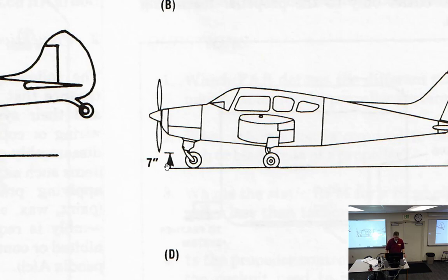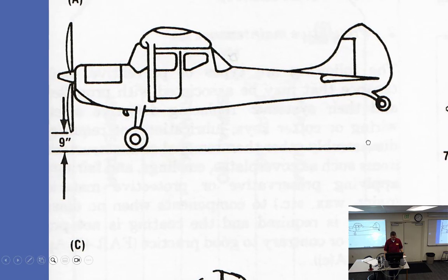Okay. Tail wheel, also known as conventional. Minimum of 9 inches at taxi takeoff position with the gear deflected, whichever is least. Takeoff position is with the tail up, so the nose is going to come down. That's going to decrease your clearance. So right there, 9 inches.